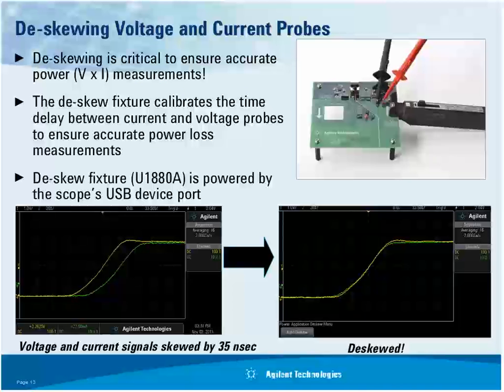Before you begin any measurements, what's very important, especially for the switching measurement, is deskewing the probes. Now, here you can see a current probe. This is a clamp-on type probe. That's a typical type of current probe you're going to use for these measurements. And here, you can't see the high voltage differential voltage probe, but you can just see where they're connected.